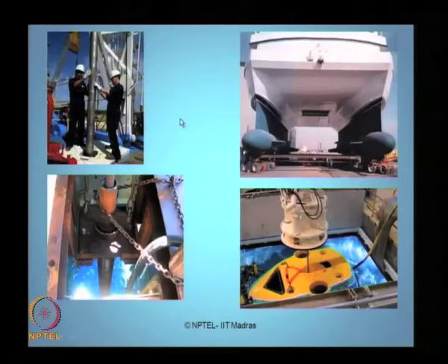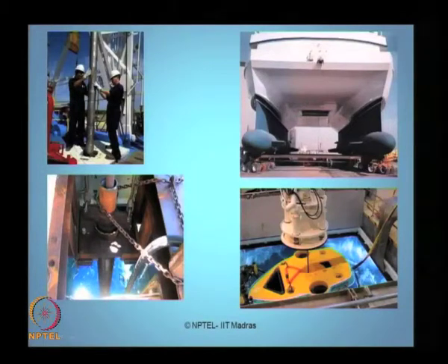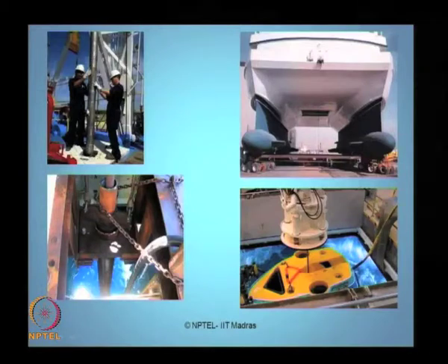These are some of the photographs which will show you the details of the moon pool. You can see here the moon pool is nothing but a hole which is driven on the top of the hull which passes through and through. You can see the water bed here, you can see the sea surface here. This is a very specific drilling mechanism, where the drilling risers are connected in pieces as the drilling progresses deeper and deeper.